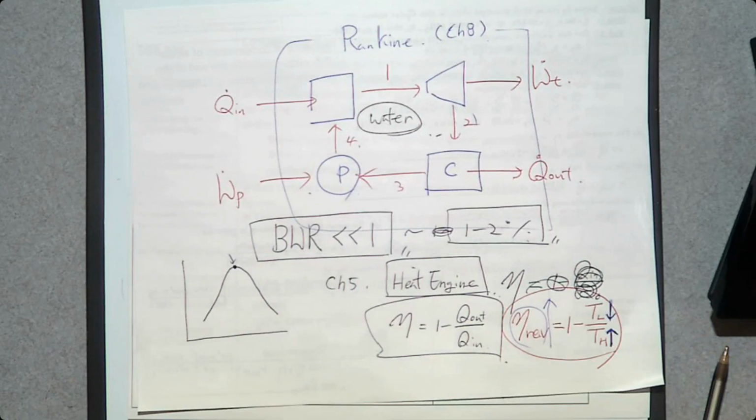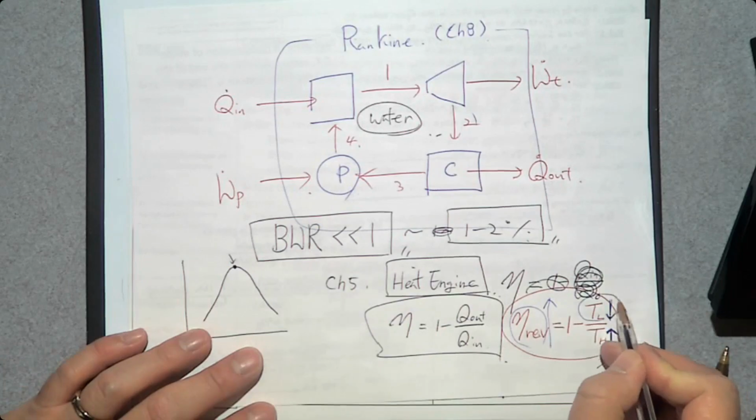So can we decrease the temperature of the coolant? Not really, because we are using the water from nearby river or lake or ocean, and the temperatures are almost constant, so we cannot decrease the temperature of the cooling system.